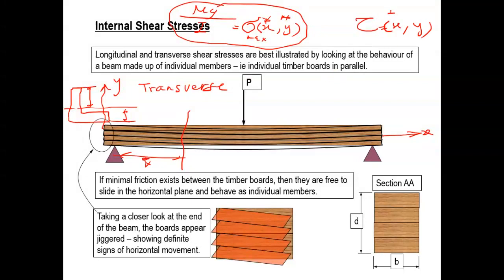So let's call this x double star and y double star. Why did I choose them differently? Because wherever the normal stress is maximum is not where the shearing stress is maximum. There are two. At the end of the day, once you have both values, you have to compare which one is larger. The one which is larger is a more serious threat for crack growth.